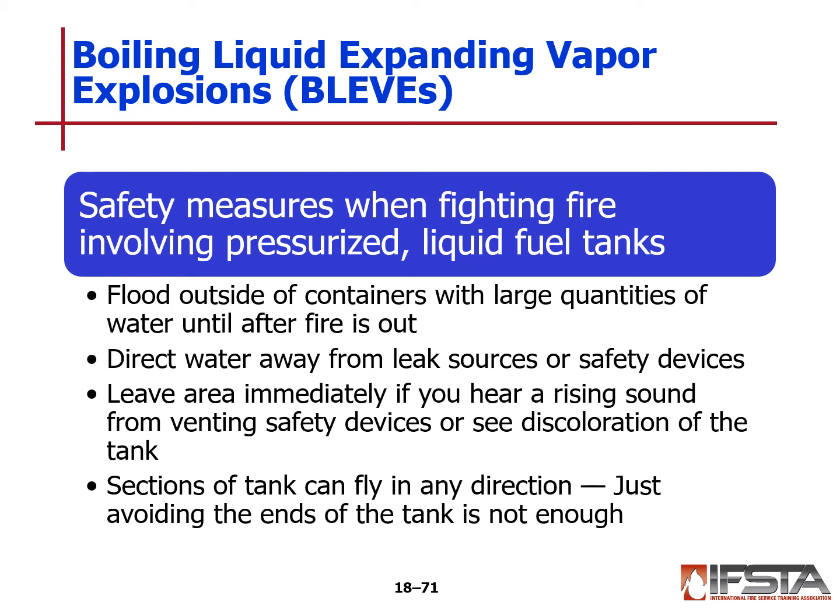We want to leave the area immediately if you hear any rising sound, hissing sound from venting safety devices, or you see discoloration of the cylinder or the tank. Sections of the tank can fly in any direction. So just avoiding the ends of the tank is not enough.